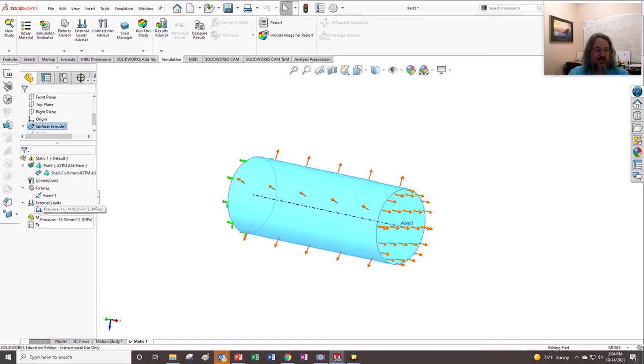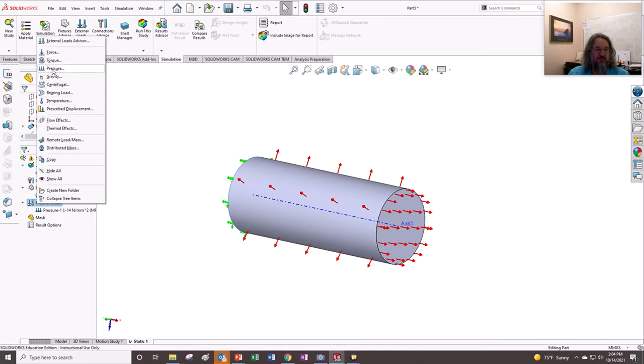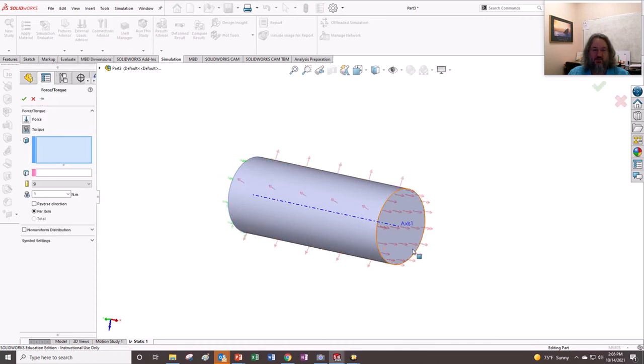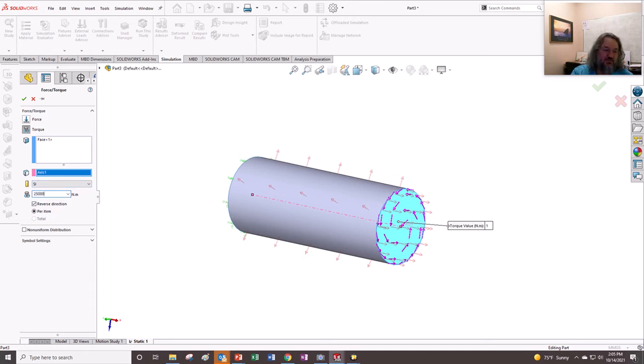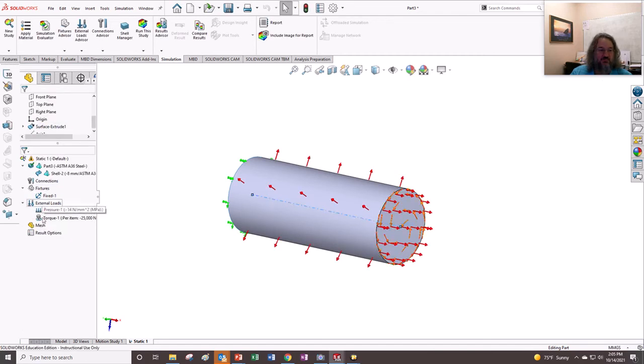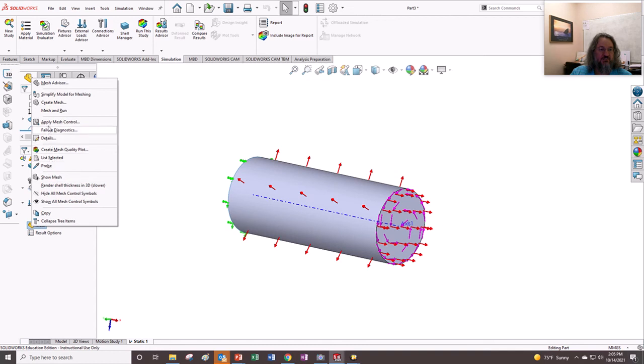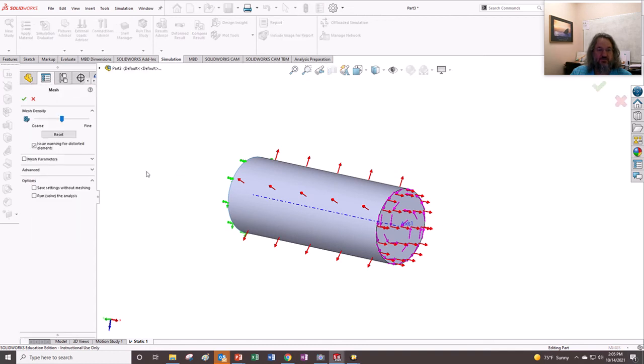And then I'm also going to put the torque onto it. We're going to apply it to this face and use about that axis. It's going to flip the thing around, and we know that it's 25,000. Did I do too many zeros? I think I did 1, 2, 3. There you go. Without the comma, I can't tell. Boom. And now mesh it. Create a mesh.